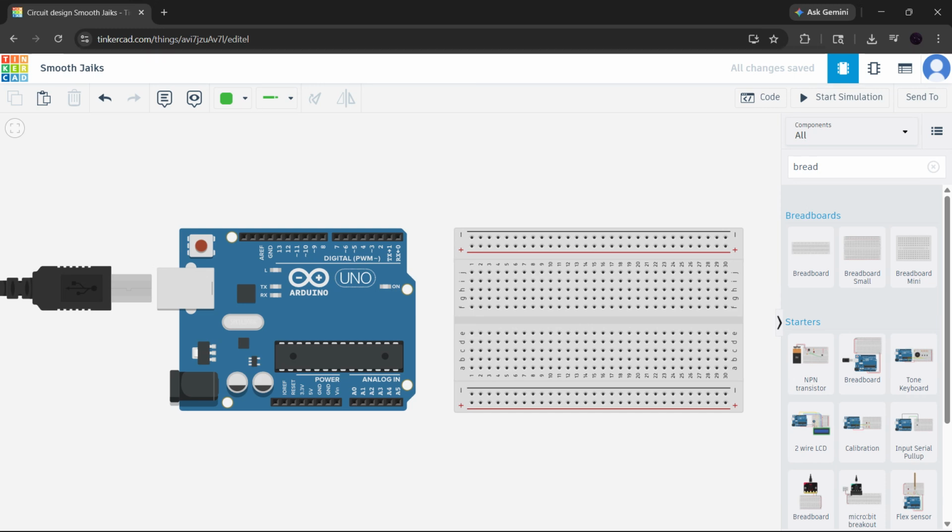If you found a custom component in the Tinkercad community, the process is a little different. For example, if someone like DrakerDG created and shared a part in a community project, you may need to drag it from that shared project into your own workspace if Tinkercad allows it, or search for it inside the component library if it has been published as a custom part. In other words, you're not importing an external file in the traditional sense. You're either reusing a shared community component or finding it through the built-in search.